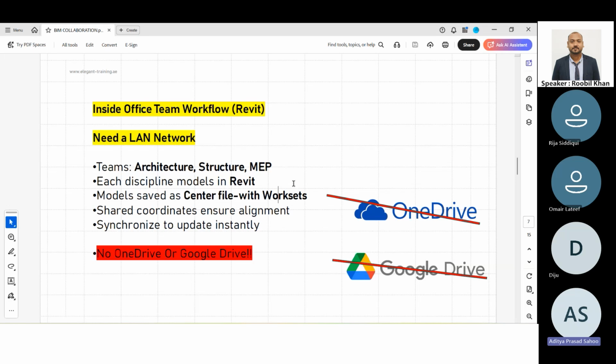That means, for example, this Revit LAN network allows users to work in one project. But for example, if all the teams want to work on one wall, then that's not a possible thing. They can work in one project, but they cannot work at the same time on one model element, like the walls. So in that case, if one team is already working on that one and the other team wants to work on that thing, they need to put a request.